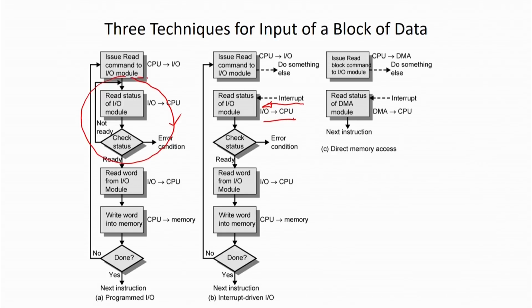Then the IO transfer happens. In that way, we are eliminating the busy waiting state, where the processor is busy but doing nothing. We can eliminate that, and the processor can now do something else, provided it is available. Once this is done, the remaining portion is the same. We transfer the information from IO devices to the processor, or from the processor to IO devices, and finally we come out. Now, we are going to see the issues related to designing this interrupt driven IO.